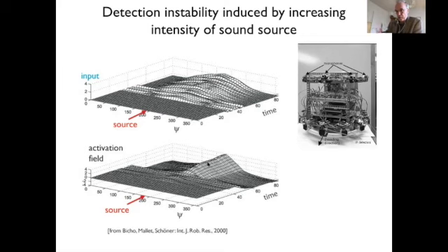The field needs to integrate that transient going to the new state. Also the amplitude of the peak is somewhat dependent on the input amplitude, as you saw in your own simulations. And you see most clearly that it's a self-stabilized peak because of the inhibition. You see here on the side how the field goes below resting level as the peak forms by inhibitory interaction. So this would be a suprathreshold peak. If we apply the sigmoid to it, that would return something positive, and then we will drive the vehicle motion from this peak.